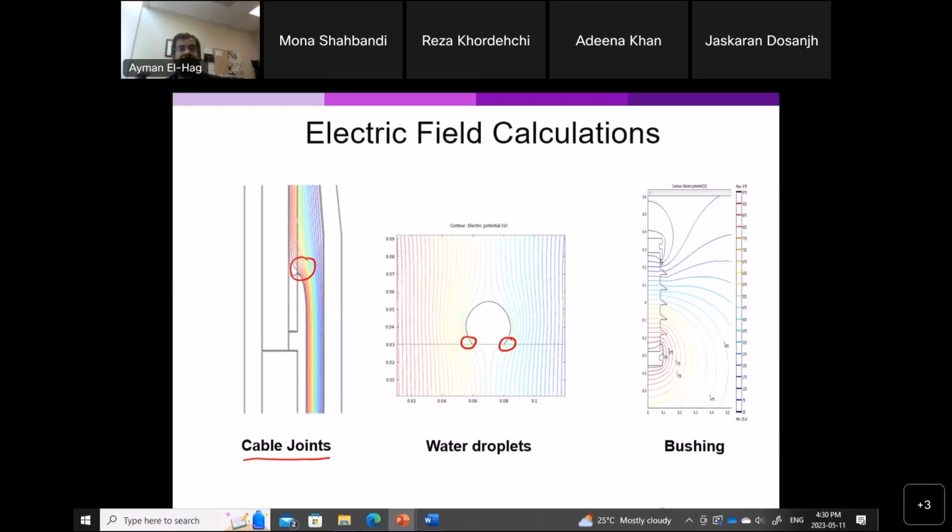So that is the most important thing to do as a high voltage engineer: to model your device. You want to see where the highest stress is. Is the stress high enough to start to cause ionization or failure of the equipment? And if it is high enough, how can I relieve this stress, how can I reduce that stress? There are certain techniques, we'll talk about them later on. So that is the first aspect, the design stage.